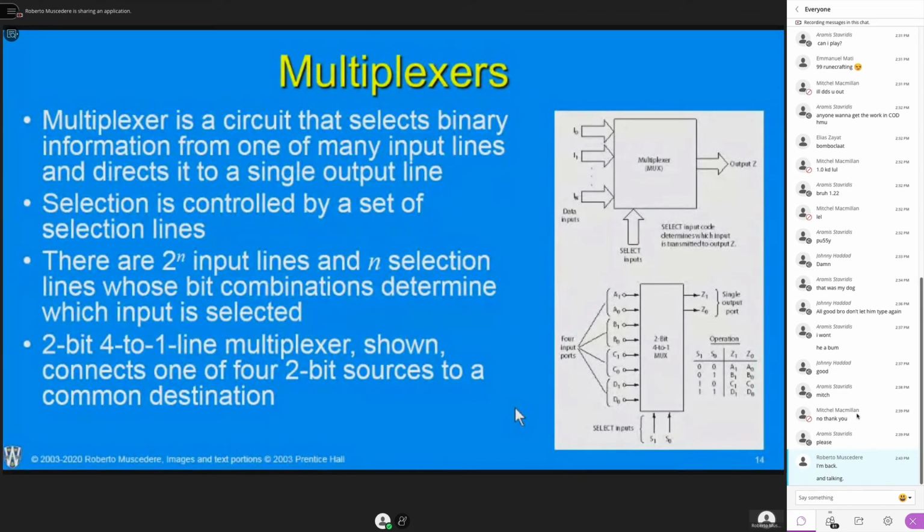Right? So we'll have some kind of circuit that will decide which one is going to move on. The multiplexer actually does the work of moving that data through. Now, again, this could be replaced with tri-state gates, but again, there are some little issues there.